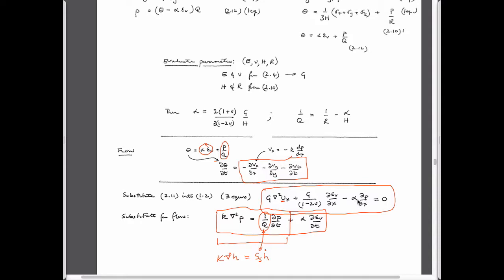Right. Okay, so the reason for kind of throwing away all that we've done to be able to now use these equations is to figure out how we might do this in COMSOL. And so if you take the fact that we have one equation that satisfies this Navier equation, which satisfies conservation of momentum and the constitutive relationship, then the only thing that we need to change is going to be to have a term on here that represents the body forces. Some term that looks like a coefficient between 0 and 1 times pressure gradient. This is all we need.